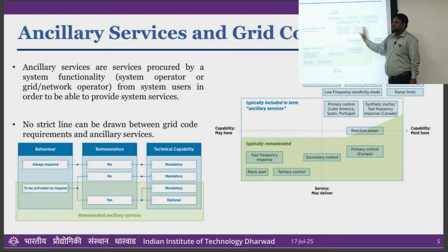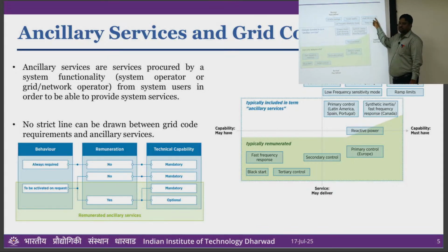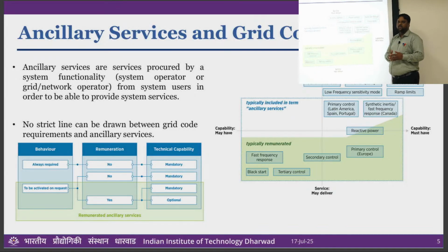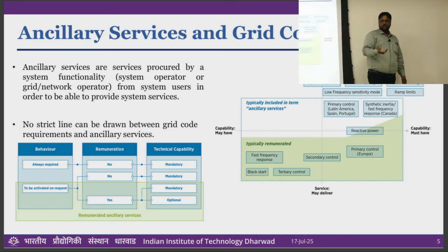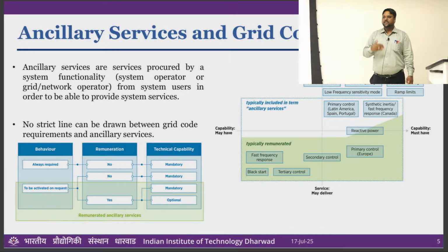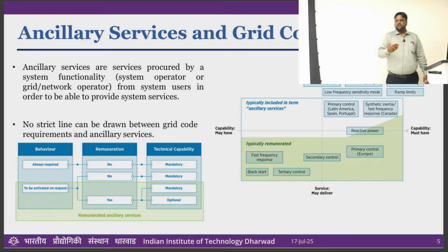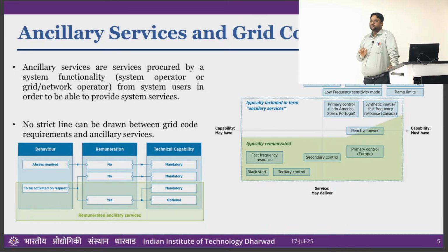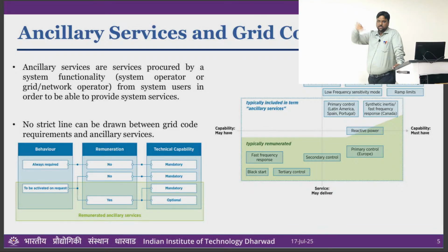Mostly your primary control, active power control, reactive power control, fault ride through, these are like abnormal voltage conditions. You have a fault happens, how you ride through the fault. Then power quality, what we discussed, some voltage quality or current quality you have to maintain, and then some kind of ramp limits again, because you inject the active power, but there is a way your active power injection should follow, the rate of change of active power, that slope, that is basically the ramp limit.